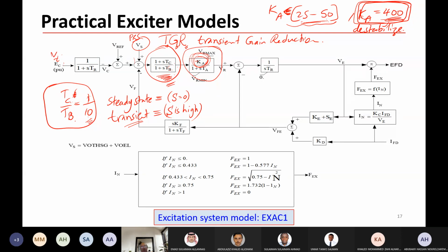No, I mean, you are running, the plant is operating, and we have any disturbance in the terminal. If you want, for example, to increase the terminal voltage, if you apply here a step input, the voltage was adjusted to 1.01 per unit at the generator. I want to raise it because I have overloading and voltage drop somewhere or some weak areas in the system.